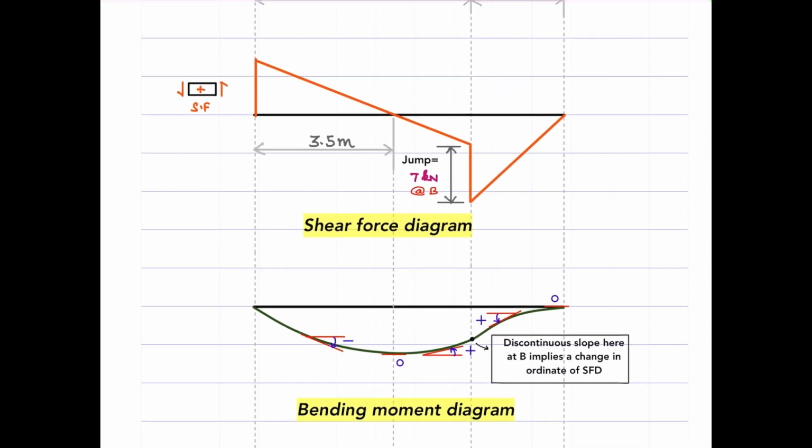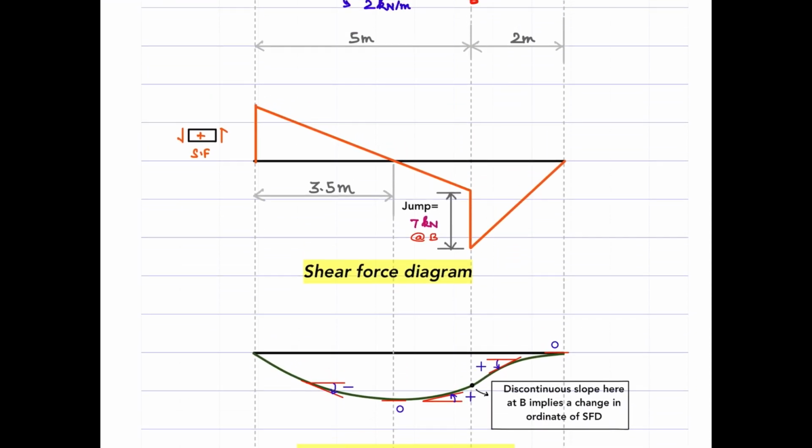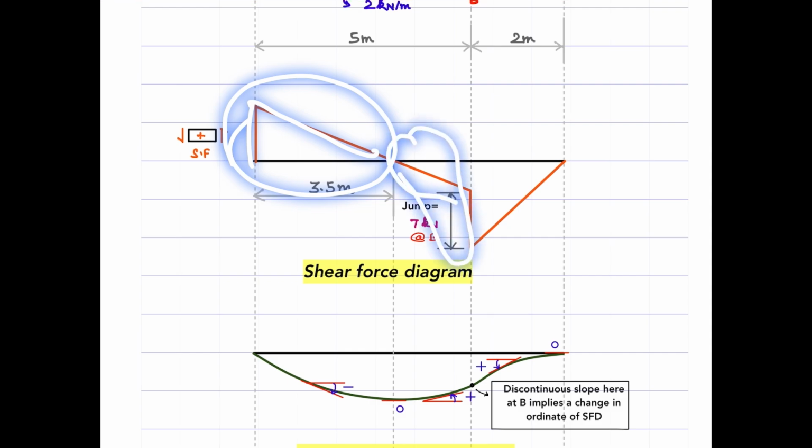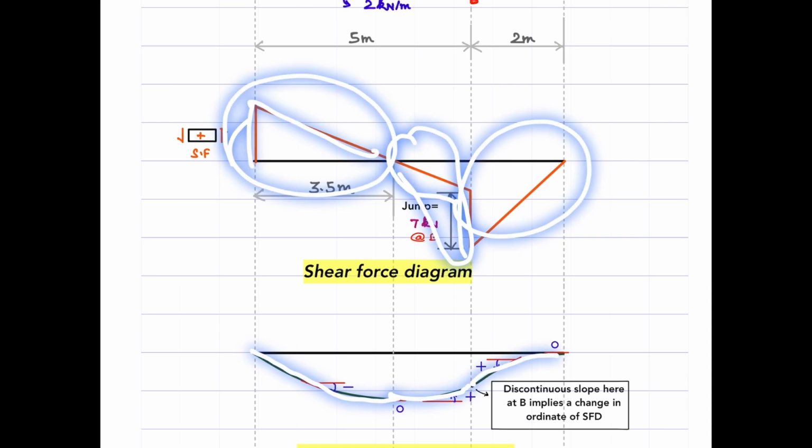How does it affect the bending moment diagram? So the trend remains the same, okay? However, we need to consider only three portions here. In the previous problem, I told there are four variations of bending moment, but here only these three, okay? Maximum to 0, 0 to a negative max, okay? And then negative max to 0. So we only need to consider these three trends, 1 and then 2 and then 3, okay?